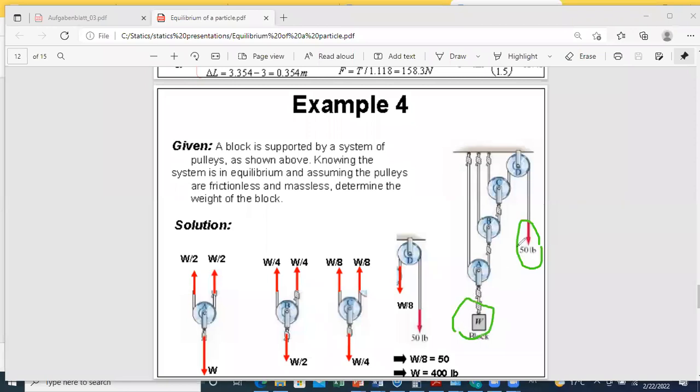Okay, why? Because you will use this force over several cables. So this will multiply the effect of this force. Let us see how. And if you just look at first sight, maybe at the figure without doing the analysis, you can say if I put 50 lb, I can hold a 50 lb weight. It's wrong. Okay, because you have a system of pulleys that will multiply the effect of this force. How? If we consider first, we are applying 50 lb at this level here.